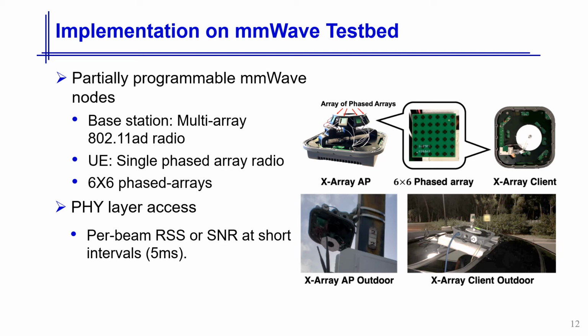The commercial off-the-shelf network interface card does not provide users with per-beam RSS, which is essential to X-ray's AOD estimation and dynamic co-phasing designs. Hence, we hack the network interface card firmware and plant a piece of code that copies the per-beam RSS values to an accessible memory space. From there, our Python program can safely extract the values in user space, where we implement our X-ray designs.